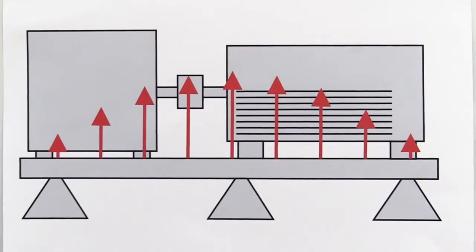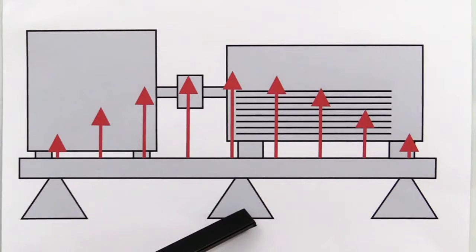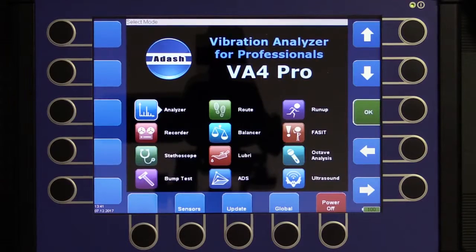The moving of the natural frequency is the solution. We reinforce the construction in order to move the natural frequency. For example, we add another pillar in the middle. Using of bump test module is very simple and also the beginner can do it.